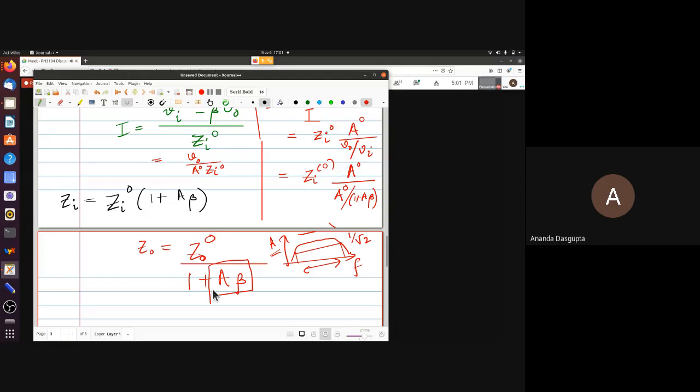But the reason I stress negative feedback so much is that an op-amp has an immense gain. Compared to the gains we have been talking about for the transistor amplifier, the op-amp's gain is way, way more, say in the 10,000 to 20,000 range easily. But the great thing is you never use that raw gain. If you want an amplifier, you put negative feedback on it. That makes op-amp circuits very easy to decode and figure out what they do. It also makes them very good in terms of stability and other desirable things.